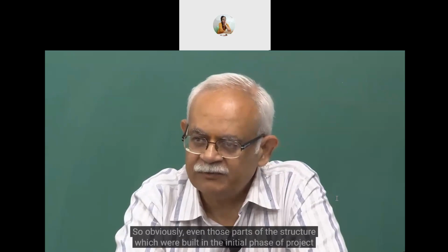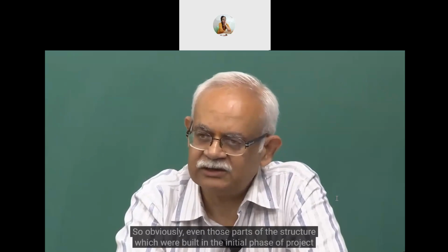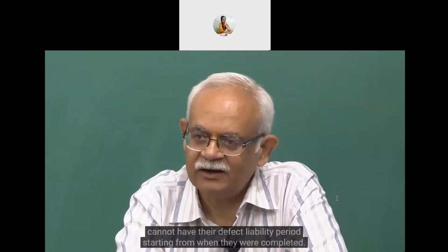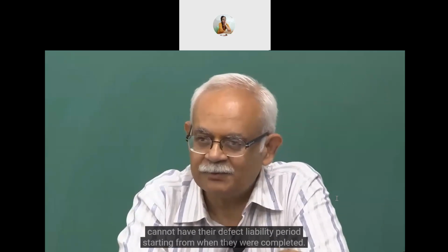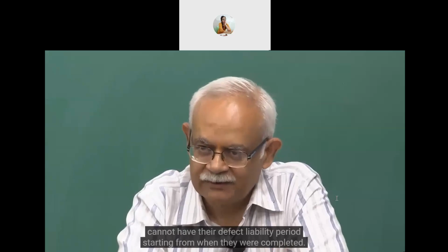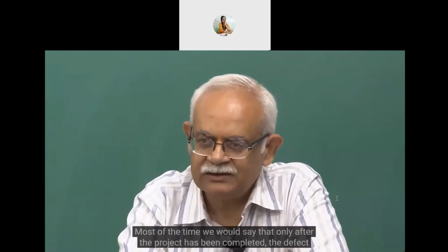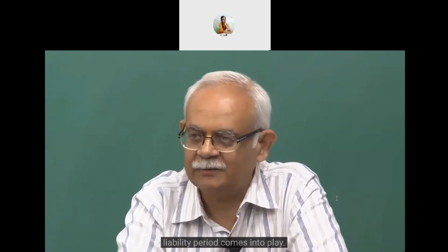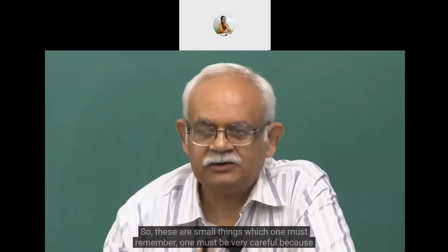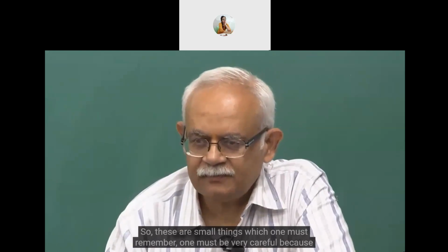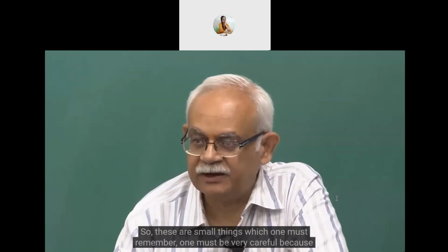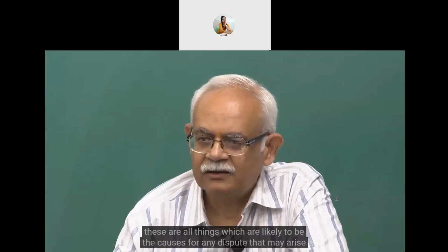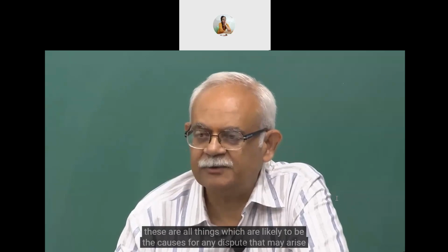Obviously, even those parts of the structure which were built in the initial phase of the project cannot have their defect liability period starting from when they were completed. Most of the time we would say that only after the project has been completed does the defect liability period come into play. So these are small things which one must remember and be very careful about, because these are all things which are likely to be the causes for any dispute that may arise with the contractors at any point in time.